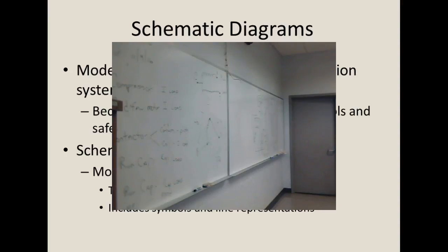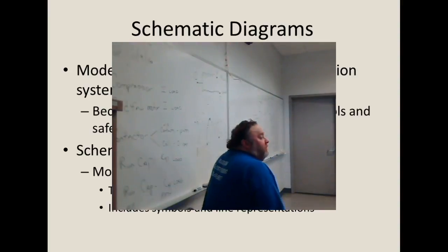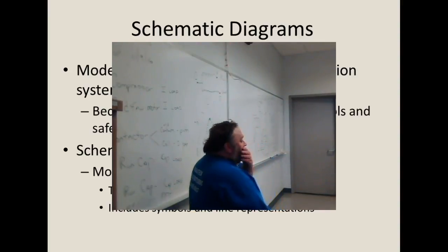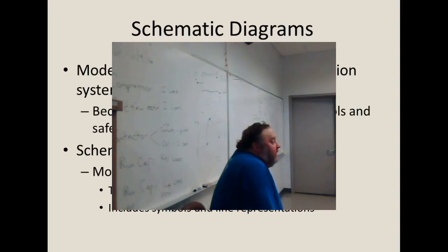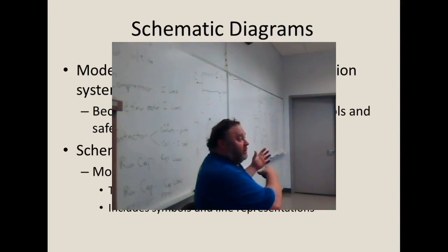All right, now, do you see where it says start and run? I want you to give me the resistance on that compressor of the start winding and the run winding. Now look at this. On this example, what would be my start reading? 2.4, right? Because 3.2 is both of them put together. Which one would be my run? All right, so everybody understand we're going to do our lab. And next time we'll do one for just a little fan motor, but we're going to start with the compressors.